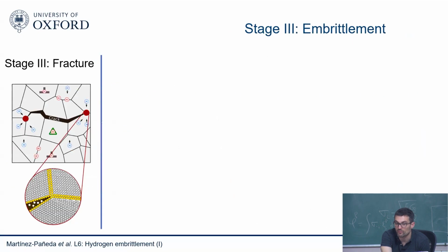And the vanadium carbides have worked, so that's, I think, a good indication that it holds for a finite amount of hydrogen, not for an infinite amount of hydrogen. So I think it's an indication that somehow the trapping is dominant over other phenomena that may happen.